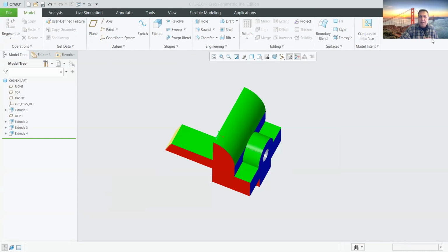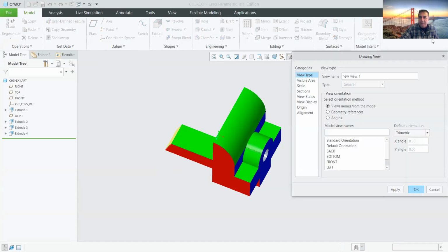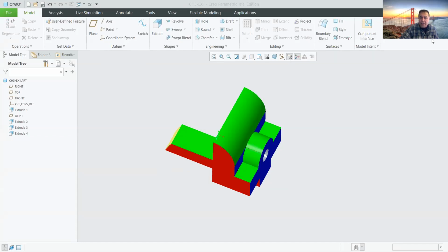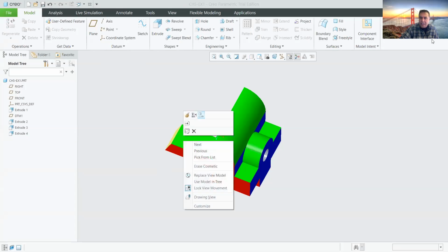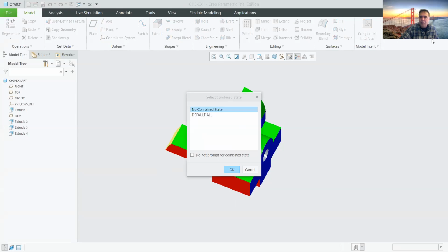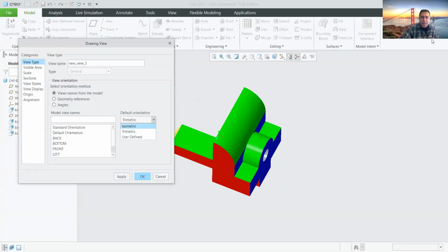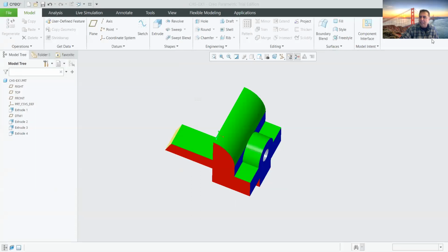All right, so now we're going to bring in the two views. The front view, general. We go to general view under the sketch here. I'm going to place the front view first, and then right click on this front view, and there is a tab here called projection view. So that's our projection view. Then I'm going back to general view, I'm going to say okay, and put the isometric. That isometric is just a pictorial sitting on the upper right-hand corner.